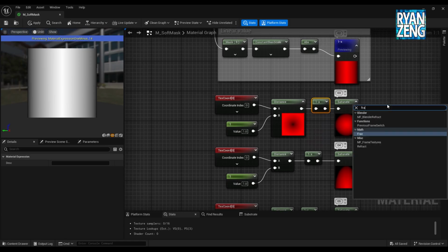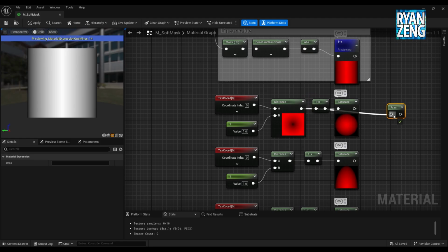You can have a quick check with the fractal value node. You can see it's over 1. So when we do a 1 minus node, we will get negative values in those corners. When you see the preview node, it looks black, but it's not exactly 0. It is a negative value, so it will cause some issues when you do multiply work with other results. So ideally, we should do a clamp. Here I use saturate to clamp the value between 0 and 1.